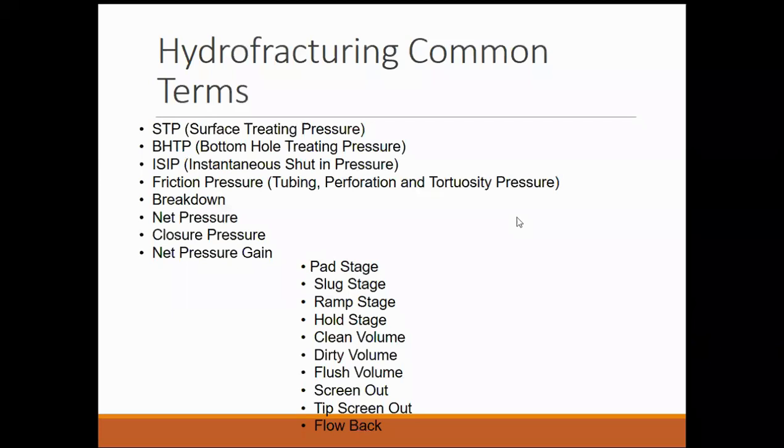You pump it first to create the frac geometry. Slug stage is a small stage in which you will pump a smaller concentration of the proppant just to check whether the formation is accepting the sand or not. Only after that you will start the actual sand stage.